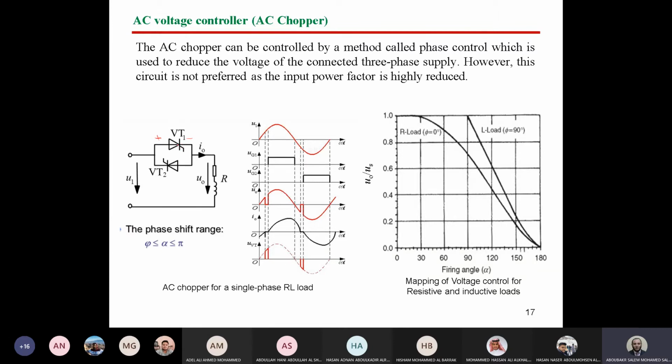This is for the diode. What about the thyristor? For the thyristor, we have to add another condition for turning on, which is you need forward voltage and a pulse that is going to trigger the gate terminal in order to turn on the thyristor. So for instance, if you have a trigger pulse at this instant here, assume we have a pulse here. Sorry, doctor, but can you repeat the conditions to turn off the thyristor? Thyristor, Shabab, SCR.